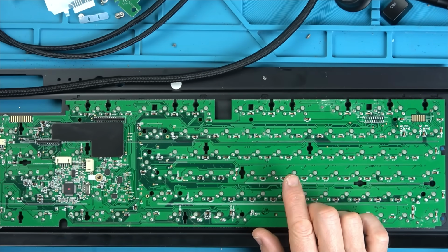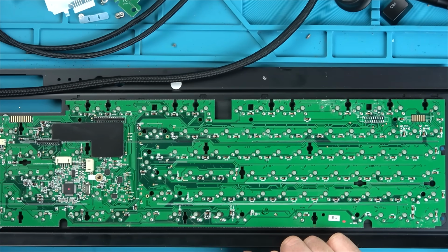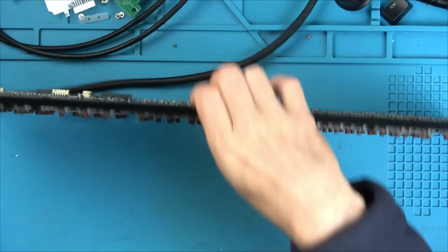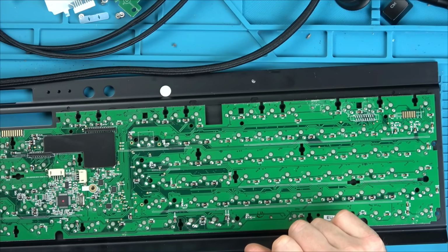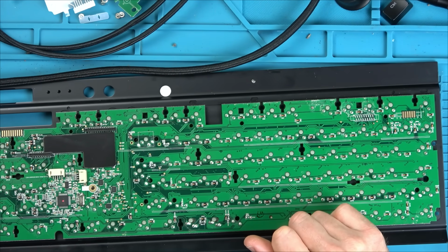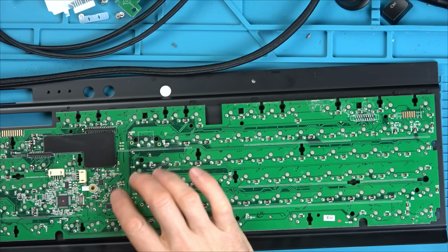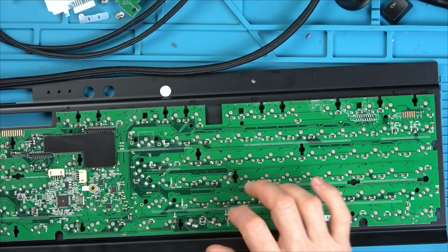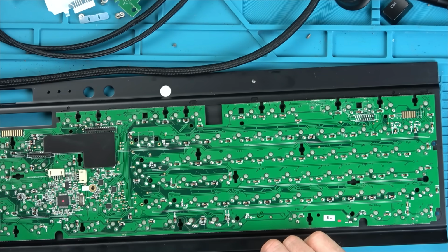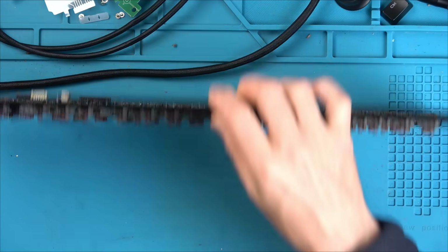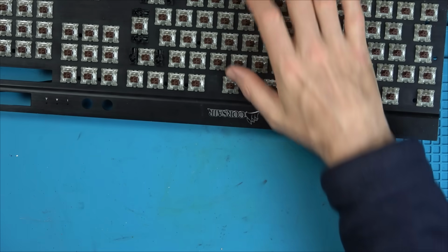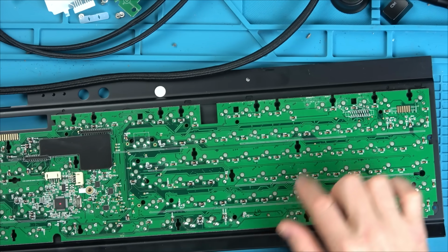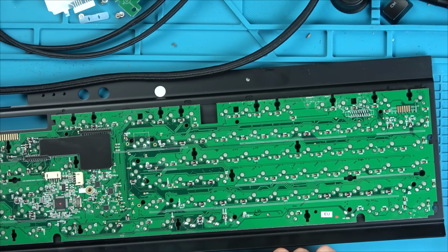So basically, the lights are not built into the switch, are they? The lights are going to be built into the circuit board themselves, which is a real shame because it's on the wrong side and I can't get to it. So now, the problem could still be to do with these chips. One of these chips, maybe on one particular pin, isn't outputting correctly to tell that one to change. Or, I think what's going to happen is there's been some sort of water damage, and there's going to be some corrosion on the line that feeds these ones that are connected together.